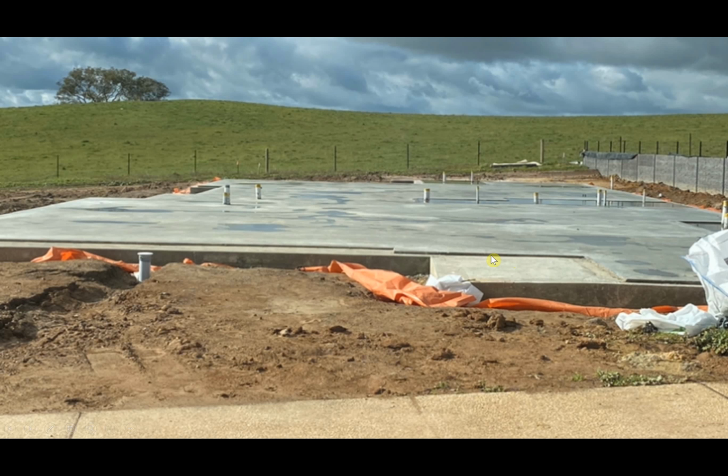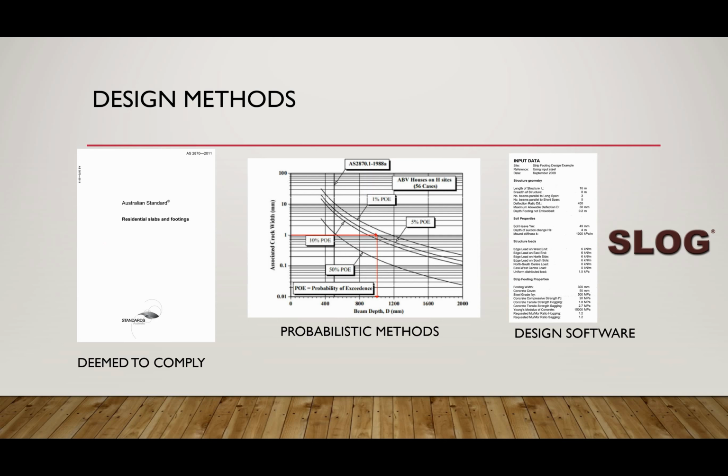We will cover this more when we look at our site drainage and our site plans when we design our levels. This line here around the building, you need to pay close attention to it. This is our set down or our edge rebate for the outside of our slab. So our brick course will sit in here. This recess here is usually 25 to 30 millimeters, which we'll go through a bit later on.